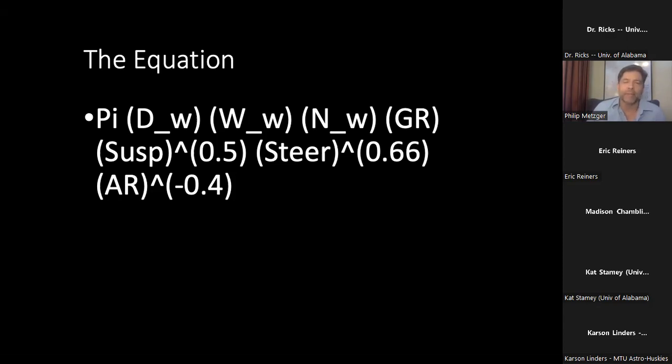Okay. So the way you drive it means don't run into rocks, don't run into craters, don't run into the wall. Don't suddenly torque the wheels from 0 to 1,000,000 in 1 millisecond. Slowly start to increase the torque so that you don't spin the wheels and shear the soil. Don't drive too fast, out of control, that causes you to skid and have an accident. So just cautious, general, good, solid driving to avoid disturbing the soil under your wheels too much. That's what I meant by that.